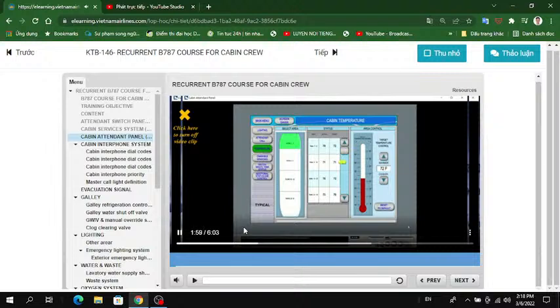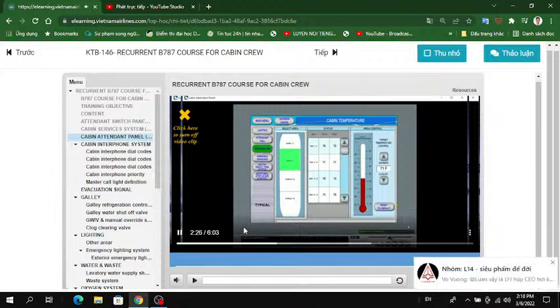This area shows actual and target temperatures for all cabin areas. One cabin area can be adjusted at a time. The warmer or cooler arrows change the target temperature. Reset to Default resets the target temperature to the temperature set by the pilots on the flight deck control panel. Select the cooler arrow. The target temperature for the selected area has changed.